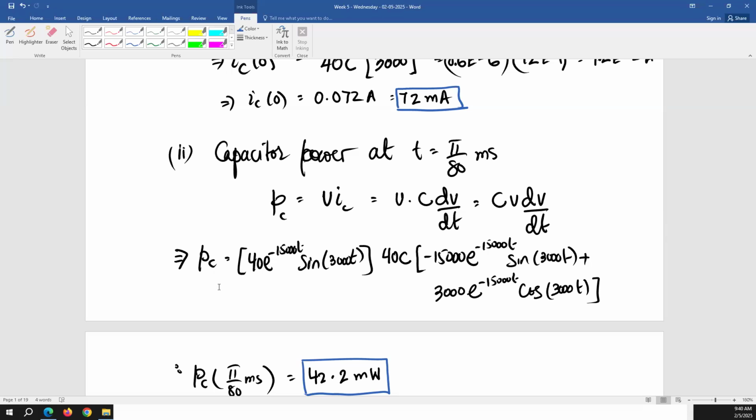It's fast, yeah. But usually multiple surge protectors, basically one is going to burn, but in the meantime the other one is going to work, because that's what they use in power systems. They don't use just one, they use multiple protections. The substation has its own protection, the tower has its own protection. So at least if one thing is going to burn, the other things are still going to be safe, by the time the energy reaches that point. Right?